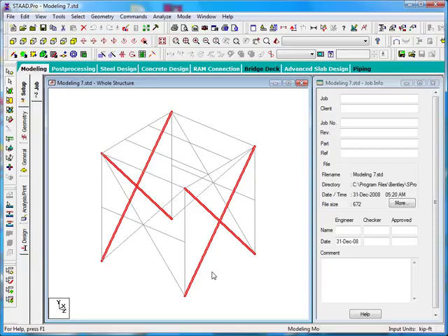2 in the front plane, 2 in the rear plane. Now if our intent at this point was to create an intersection point at the locations where those members cross, then we could just go in and use the other tool that we saw, which was intersect selected members and then intersect, and that would create an intersection between all of those members.